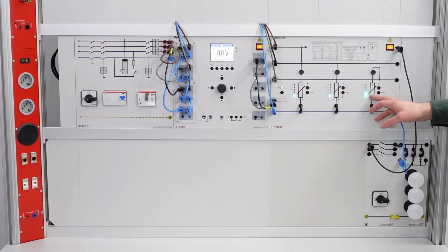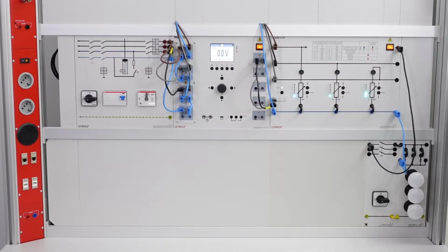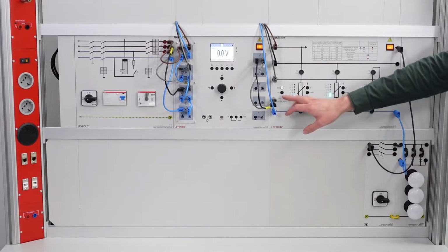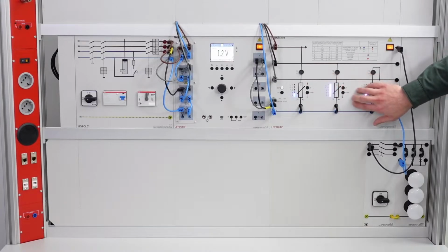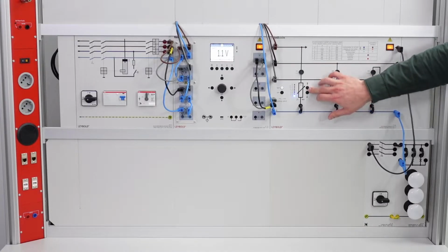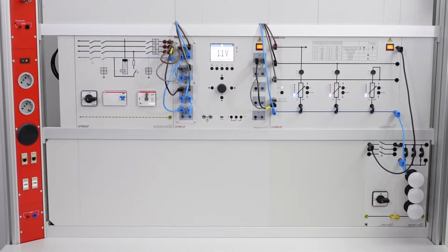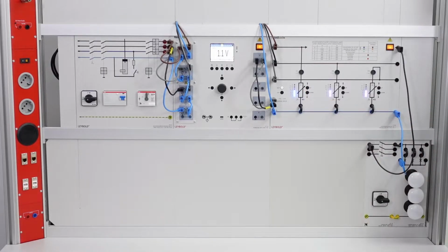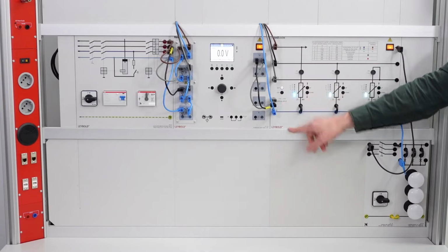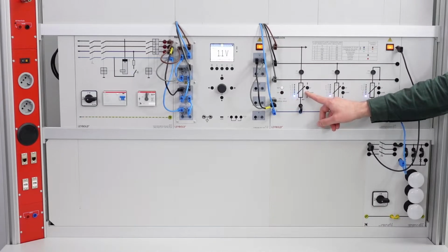In this mode, we are allowed to use unbalanced configurations, but you have to think about it because some configurations can stress your other equipment. The load can be turned off with the off button. If you don't want to use an unbalanced configuration, you can couple each phase with another. You do this by pressing up and down simultaneously, and then pressing the up button on the phase you want to couple, and now you are allowed to control all phases at the same time. You can turn them on and turn them off again.